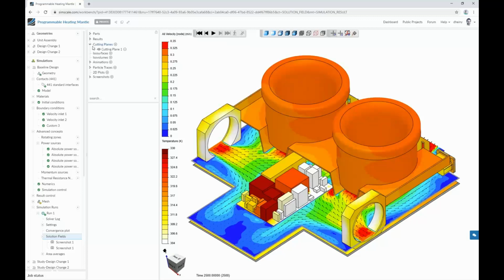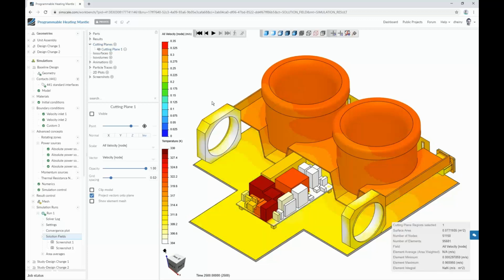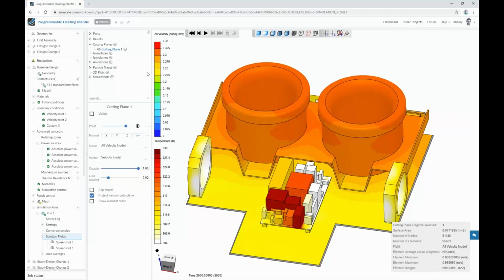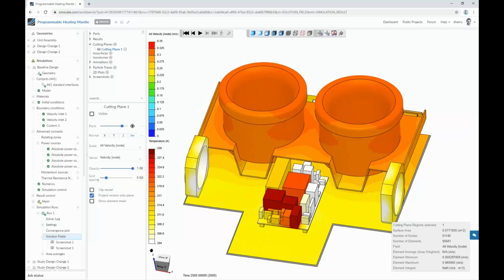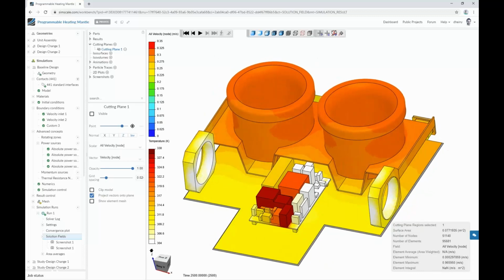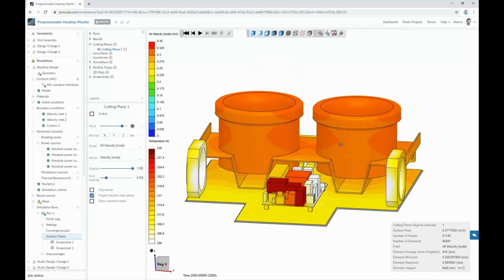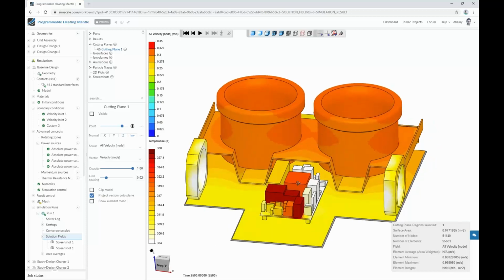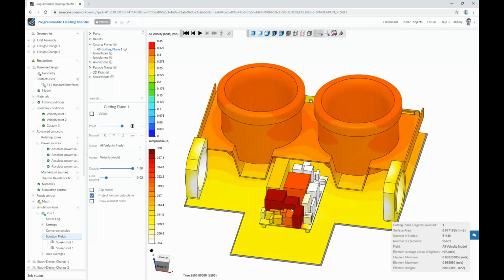All right, let's start first with just the, so you can see I saved this state, right? So I actually could now show all parts, you have the air, etc. You have everything that was simulated. You can slice and dice and take a look at surface temperatures, yada, yada, yada. In this case, this is now a surface plot of temperature, right? 330 Kelvin is about 50 degrees Celsius. So we can see already, okay, that's going to be a problem, right? An electronics component that goes north of 50 degrees Celsius. In this case, we're considering that a limit.